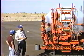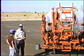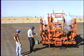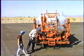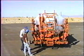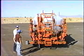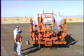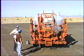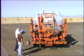That's not anything that you have to think about as an operator. The only part you should think about as an operator, anytime you're out of the truck, if you're out here at the back of the truck, that equalizer valve, the main valve there, should be in the closed position. And it's just a good habit. If you're back here and you're assuming that the spray bar is circulating, say we're on a job where we're spraying paving grade asphalt, you're out of the truck, you're waiting on the rock crew or whatever, you're assuming that it's circulating. The pump is sitting here turning.